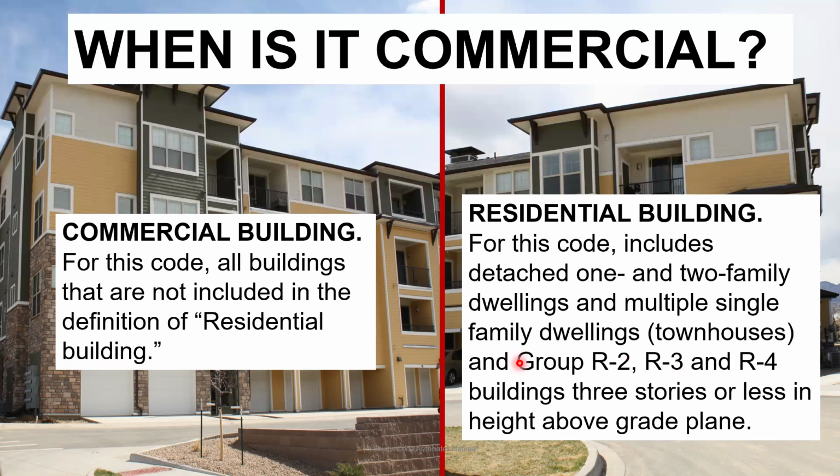So we can have that same R2, but 4 stories tall, like we have on the left here, where we have a garage story and then 3 stories of residential building above. And that is going to help trigger those requirements for that commercial building application. I think that's especially pertinent when we look at that exterior energy use, because oftentimes that really falls in that multifamily category for some of these appurtenances, like pools and spas, and the typical places that we'd associate that with. Usually we see those permitted with some sort of clubhouse structure, some sort of B or A3 occupancy that's tying all of this together.